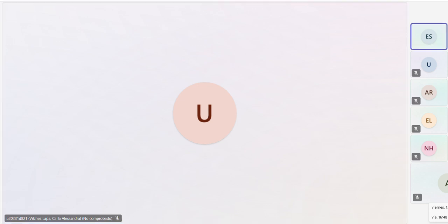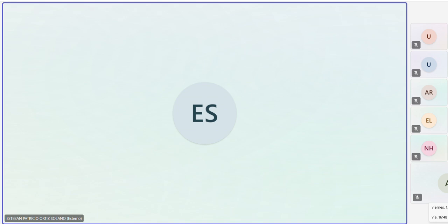Okay, I'm not hearing very well, but more or less I got the question. It's extremely complicated to introduce anisotropy. One way is to introduce on purpose different arrangements of the stiffness of the material. In my case, what I did was combine a stiffer hydrogel with a softer hydrogel. In that way, when you apply the load, it is going to distribute in a random way, which is more or less an anisotropy.